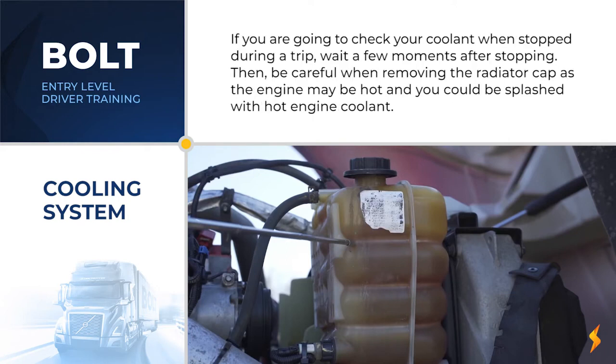If you are going to check your coolant when stopped during a trip, wait a few moments after stopping. Then be careful when removing the radiator cap, as the engine may be hot, and you could be splashed or sprayed with hot engine coolant.